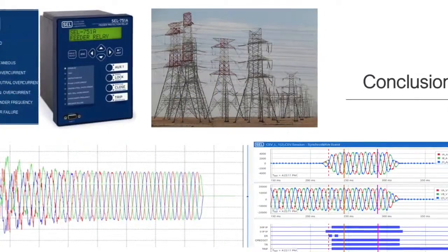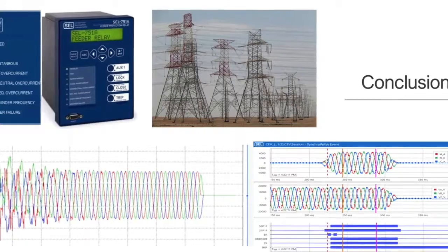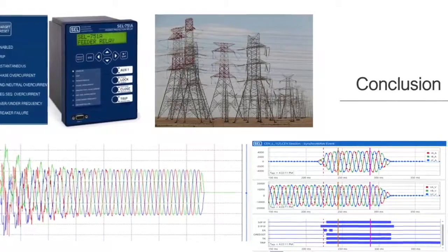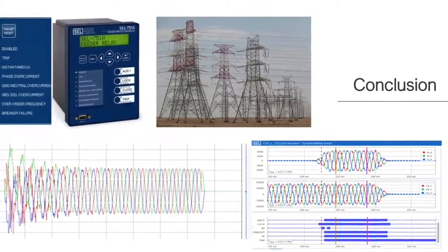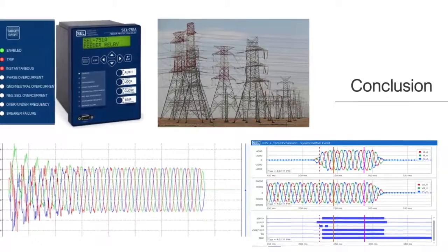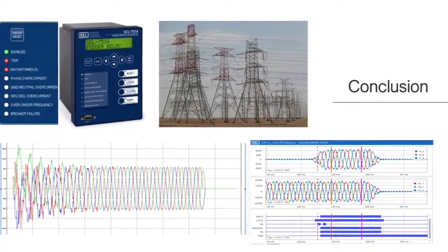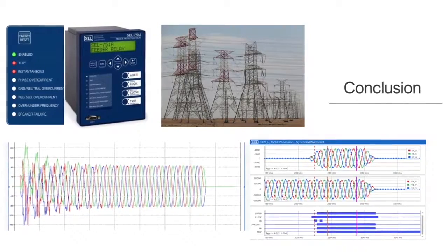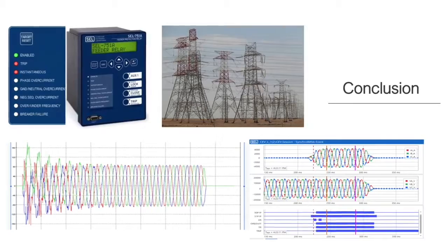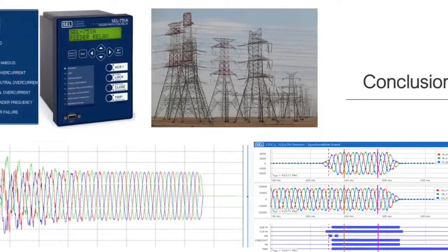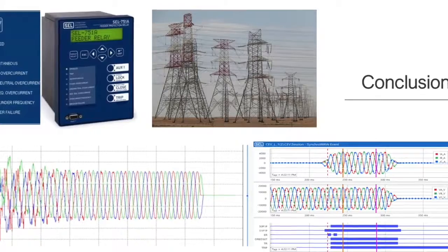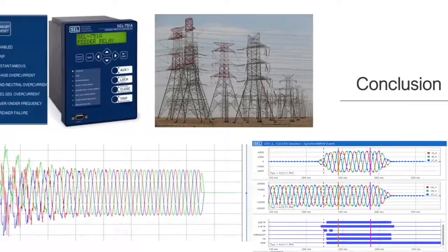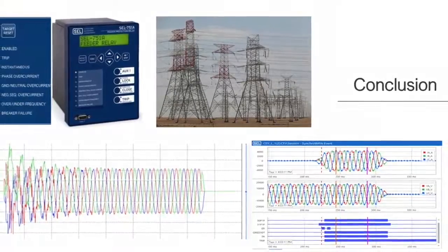Thank you, Melvin. The project is to simulate the three-phase overcurrent fault and generate the COMTRADE file for the fault analysis and uploading on the relay. The overcurrent fault analysis is done using Scope View and Syncrowave. It is observed that the fault current is much higher than the load current. The SEL 5401 uploaded the overcurrent fault on the 751 relay. The relay has settings for tripping time and time dial setting. When the relay sees the overcurrent fault in the transmission line, it trips to clear the fault. Overcurrent causes overheating in the transmission line and leads to short circuit. The project is successfully completed and the scope of the project is obtained.